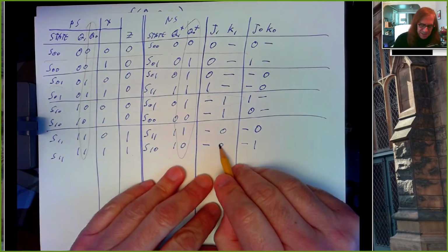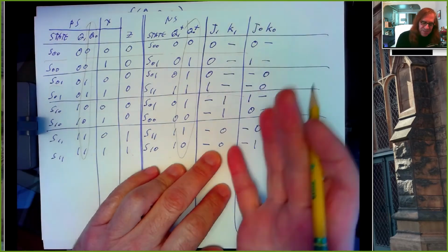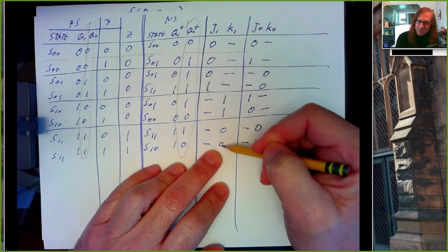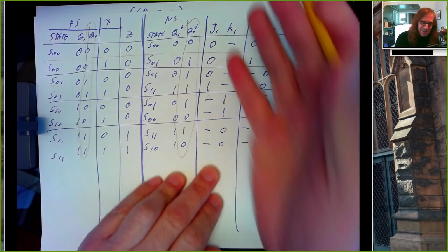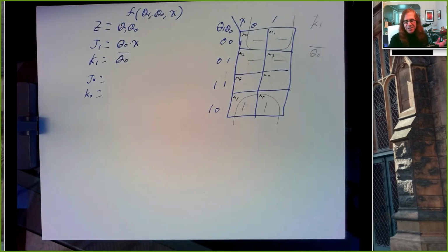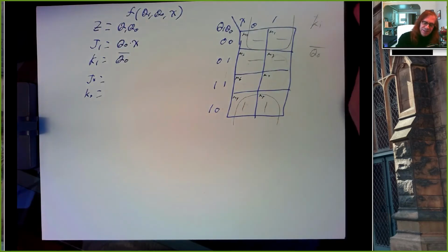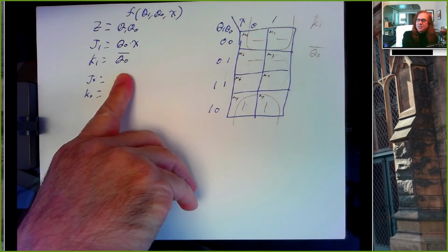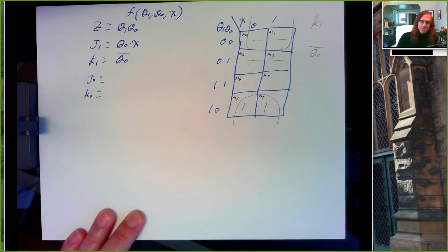And that satisfies what we've written, because we don't care about the 1, 1, 0, 0 here, but we got the 1, 1, 0, 0 that we do care about. So that's a great way to write K1. It's one inverter. In fact, we don't even need an inverter because our flip-flops have inverted outputs. So this is just a wire coming from Q0 not into the K1 input.